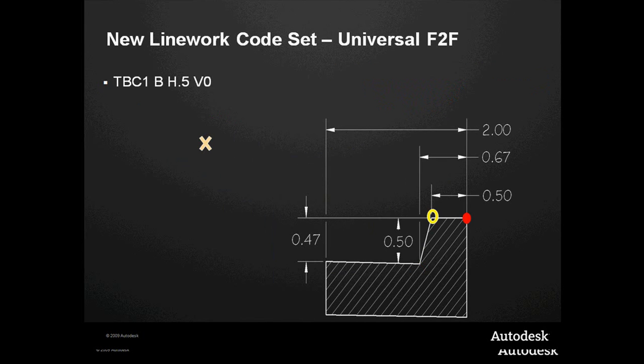As I take my shots, my first shot, the code would be top back of curve 1, begin. I'll just put in a horizontal of 0.5. I've got vertical of 0, just to make it clearer. If it doesn't change vertical, you don't need to say anything. It'll use the same elevation. So I can say horizontal offset 0.5, vertical 0. We'll step over to the next one, which is now here. Now my horizontal offset is 0.67, and I'm dropping down negative 0.5. Then I'm going to step out to the end, horizontal 2 feet over with a negative 4.7 to give it my slope of my gutter. All right, so I apply those values. That's in my first string when we collect the first shot.